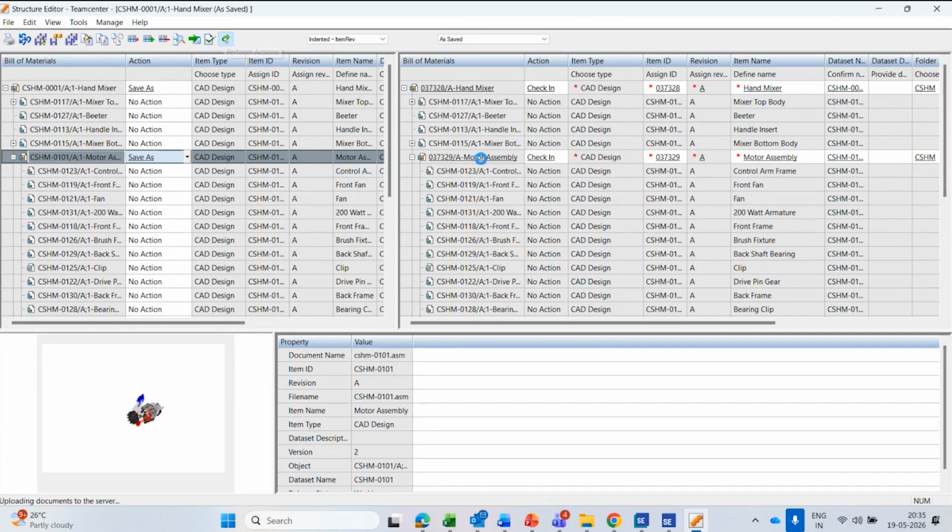But for that, the Solid Edge dataset will not get added. For that, we need to open that part and select a new template inside Solid Edge to create a new dataset for that newly added component under this subassembly here.